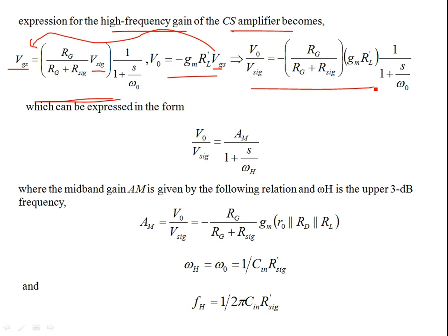So it's again low frequency. It's in the form of the response is low frequency response, because as S is going to... I'm sorry, it's the high frequency response. As S is going to increase, this is for the complete common source amplifier voltage gain. So as S is going to increase, the voltage gain is going to drop. You can see from this expression, as S is going to infinity, the voltage gain is going to drop, and that is what is expected of it.